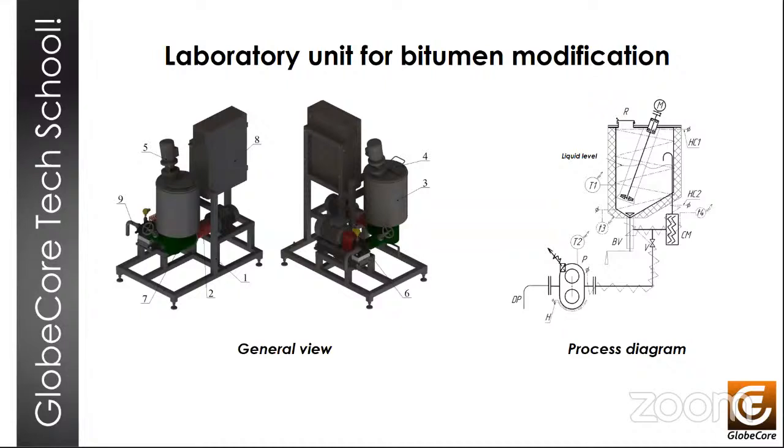And after that, the operator places a container under the drain outlet and opens the valve V and turns on the bitumen pump. The modified bitumen will then flow from that outlet. However, it's recommended to first drain the first few seconds, 2-3 seconds, into some bucket for disposal. And then you can use an actual sampling container, take an actual sample for laboratory analysis. So after draining that prepared bitumen from the tank, the residual bitumen should also be drained from the mill, from the outlet, from the pipelines, etc.